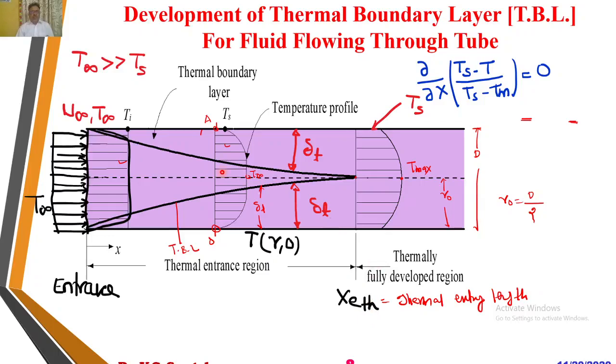The nature of flow in this thermal entry region is called thermally developing flow, because temperature profile in this thermal entrance region is continuously developing and changing.